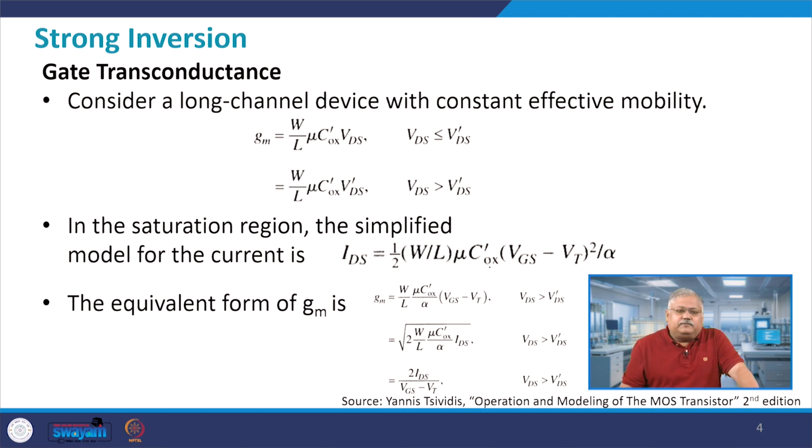You will ask me why this varies. This varies because in strong inversion you are actually having an inversion layer being formed, and therefore that sort of screens the gate from the bulk, and therefore the influence of the bulk will be relatively small once strong inversion has set in. However, that is not the case when weak inversion is there.